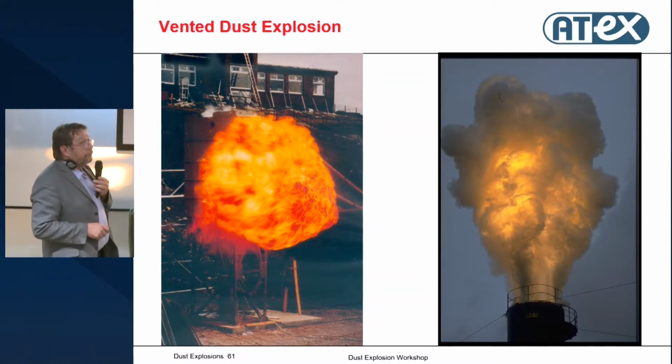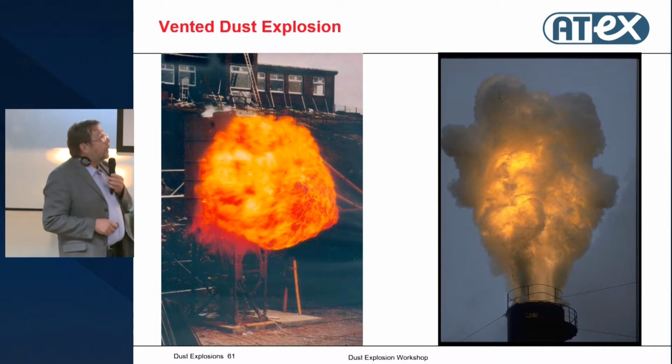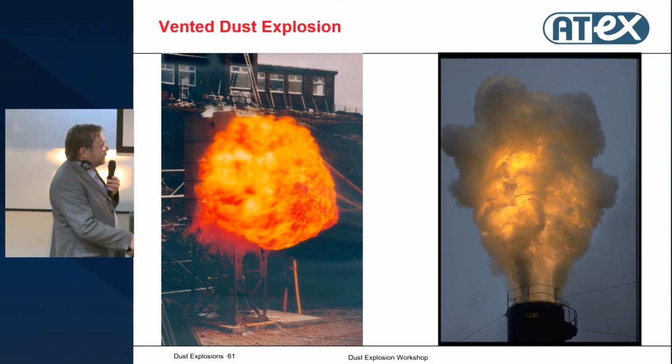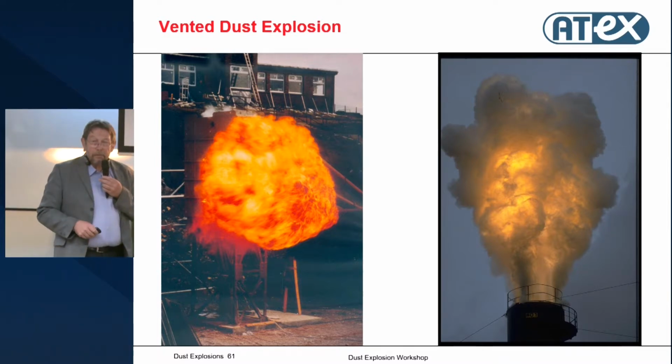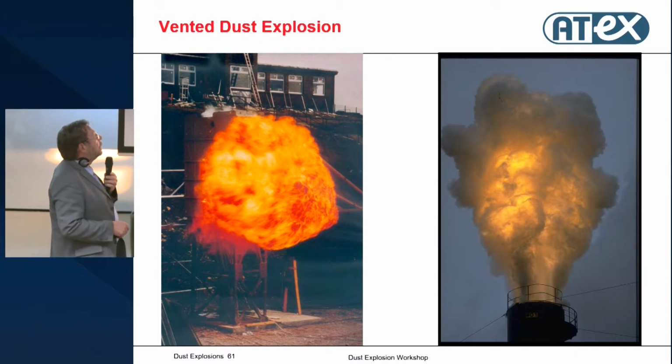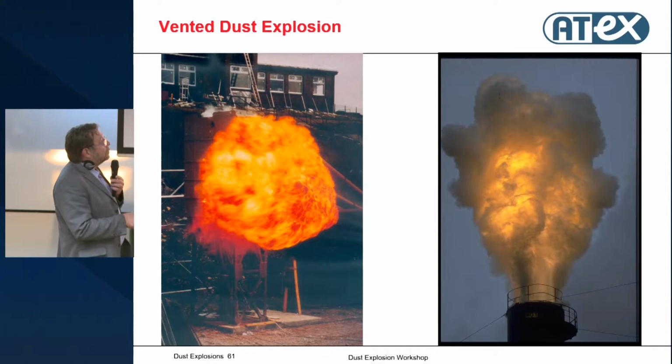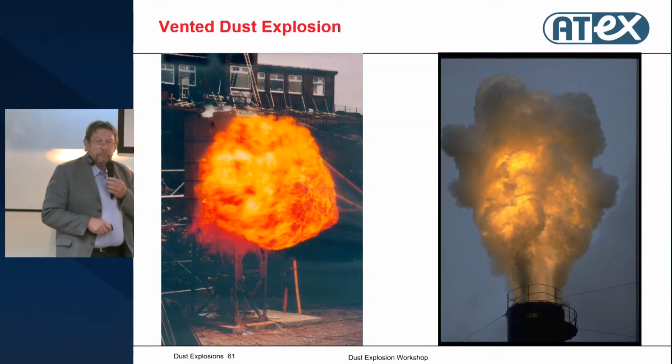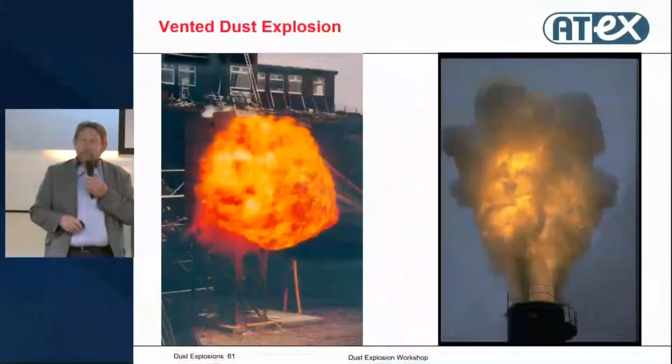And just to give you a feeling, it was an elongated silo, L/D close to 5. And we always use the same vent area. If we ignite at the top, close to the opening, we had about 25 to 30 millibars overpressure. Not very much.